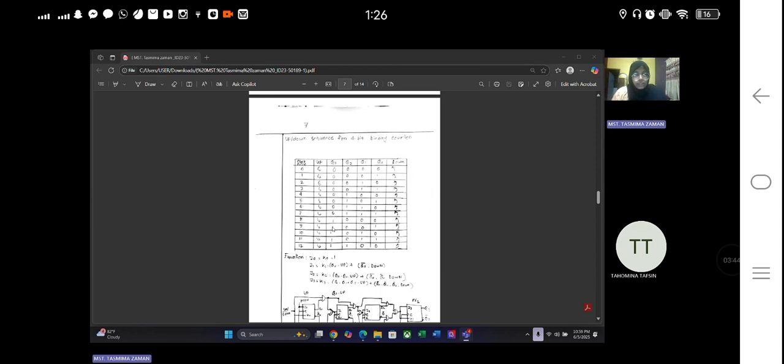It's the brain of the system, the 4-bit up-down counter. We designed it using JK flip-flops for incrementing and decrementing. For example, one of the core logic expressions is J1 equals Q0 AND up plus NOT Q0 AND down, which helps the counter decide whether to count up as cars enter or decrement as they leave.